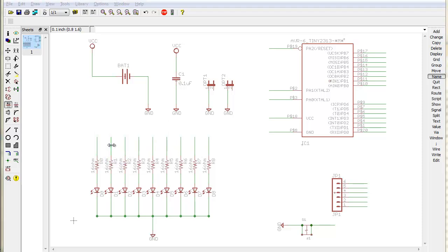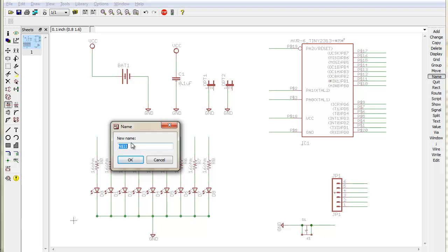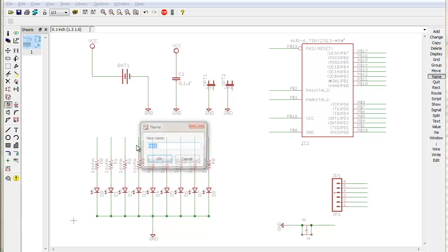Someone is asking me if a 1210 LED will fit without altering the board. It will, because I redid the pad from the SparkFun library and made it a bit bigger, just so that we could do stuff like that. So the answer is yes. However, you won't want to find out until tomorrow, because this is a recorded video.